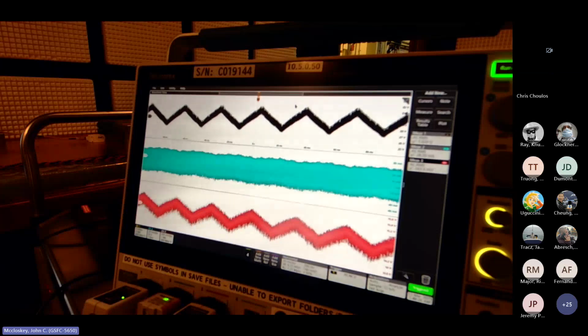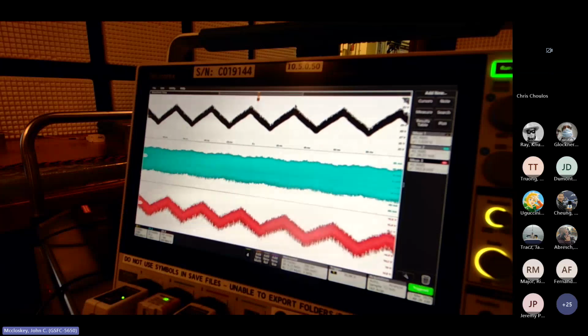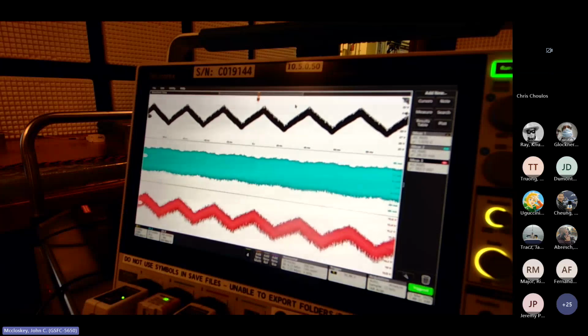So your performance metric in this case, you could just say how much attenuation are you getting? We're injecting 1 volt RMS on the input of the power converter, and we're getting 160 millivolts RMS at the output. So we're getting about 16% of the injected signal. So whatever the reciprocal of that is converted to dB. It's somewhere around minus 14 or 15 dB or something like that. Anyway, that's what we have at 30 hertz.